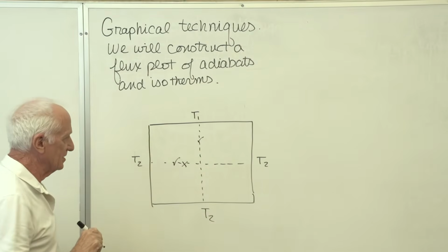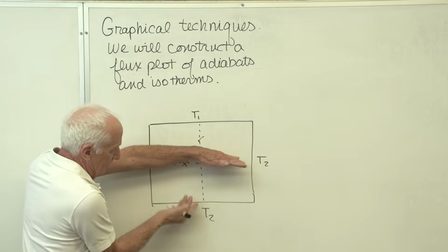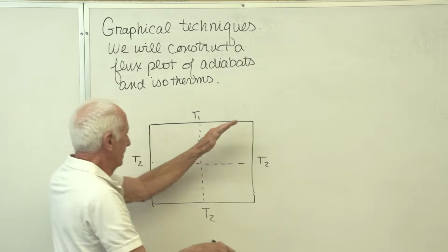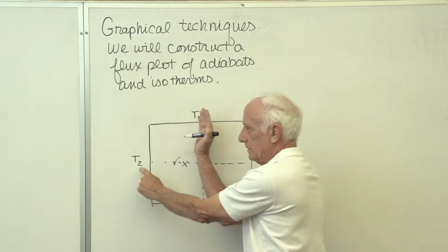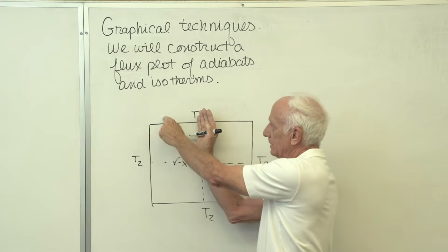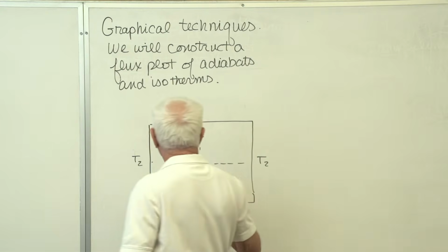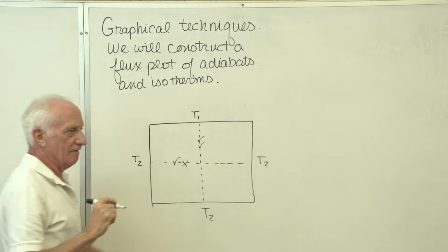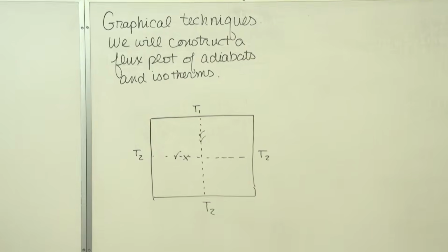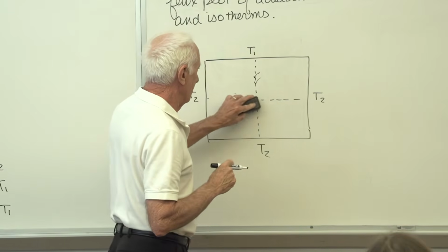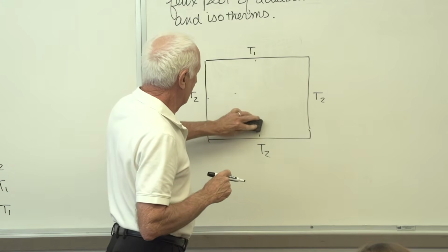It's not thermally symmetrical. Fold about here. This side comes up to the top. T2, T1, no, it won't be it. Take this guy here. T2, T2, check. T1, T1, check. T2, T2, check. Yep. This guy is a line of both geometric and thermal symmetry. He qualifies.